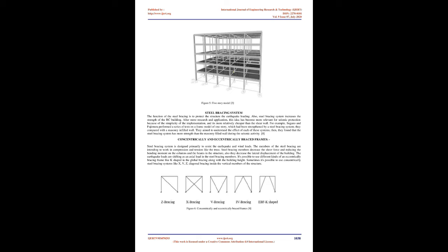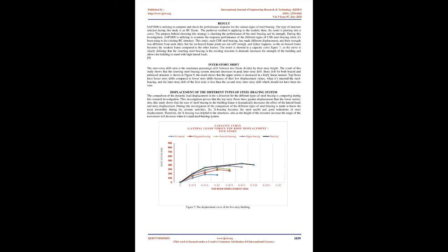4.5. Plastic hinges. The occurrence of plastic hinges in the building using the pushover method will vary according to the number of stories, also the type of bracing system and the type of plan shape of the structure. The plastic hinges will reach different limits according to the deformation of the steel bracing system because of the failure moment under ground motion. In this study, plastic hinges will be under 3 properties: IO, immediate occupancy; LS, life safety; CP, collapse prevention; and A, B, C, D, E according to the condition of the hinges. In this part, the comparison between buildings with the same number of stories and plan shape will be analyzed by the pushover curve on the x and y axes.